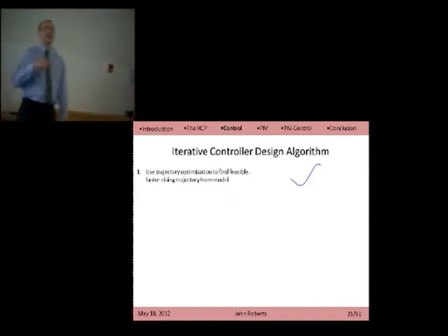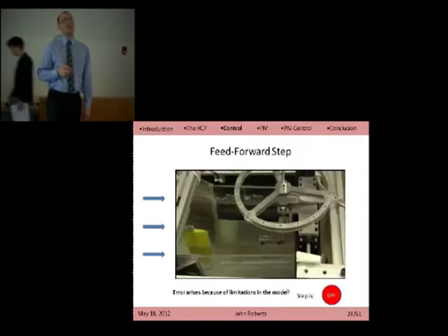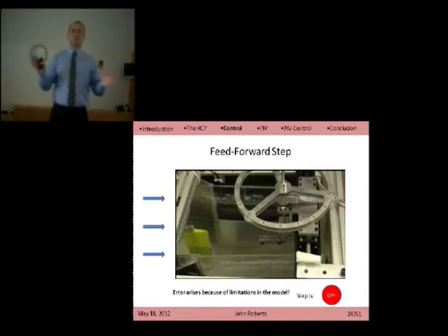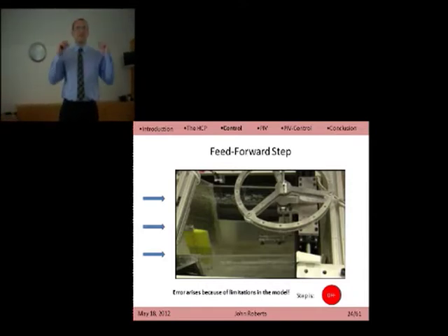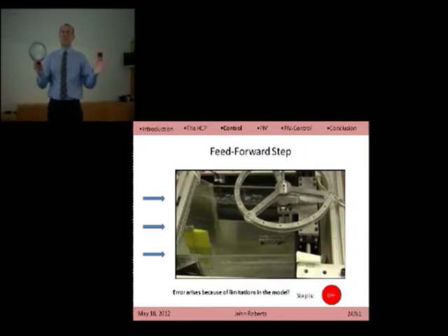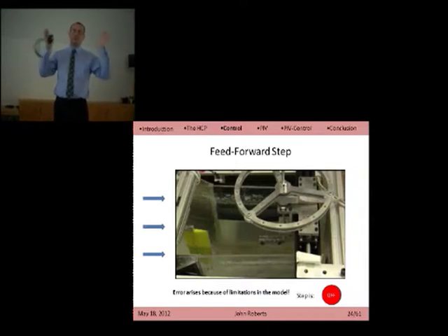So we'll follow a data-driven control kind of approach. The idea of this approach is that we're tracking a step that's not so far from what we want, but it overshoots, not exactly meeting our requirements. But we're getting data of the system near the domain we care about. So instead of trying to build a bigger model that captures everything, all we need is to use that data to get an understanding of the system locally, near a step, effectively near a 4 centimeter step. We can build an idea of how the system behaves in that domain. Then using that local understanding, we can say, okay, here's how to make it a little bit better. Here's how to reduce the overshoot a bit.